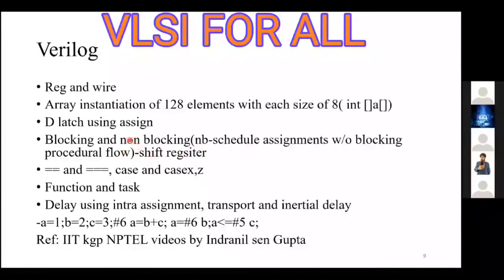A shift register is generally implemented using non-blocking. For example, if you take a 4-bit shift register, you can directly assign the input of one flip-flop to the output. It is just a connection from the input and output. Here with the non-blocking, you can directly write the statements in any order. But when you are implementing this 4-bit shift register using blocking, you need to follow some definite order in order to implement the shift register. If you follow in reverse order, then there is a probability that you will be getting a single register. So the ordering of the instructions is important when you implement the shift register using blocking.